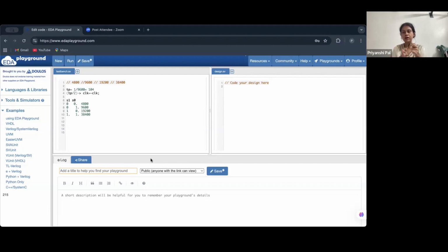If it's 0 from the master's perspective, the master would be sending the data to the slave, else it would be receiving the data from the slave. From the slave's perspective, if the data direction is 0, the slave would be sending the data to the master. If not, the slave would be receiving the data from the master.